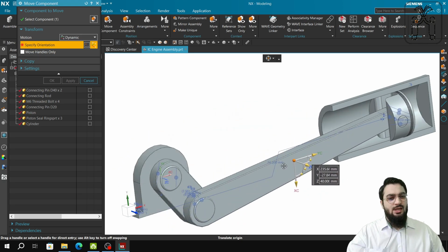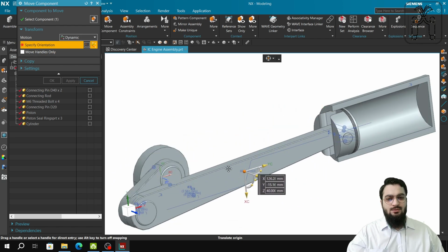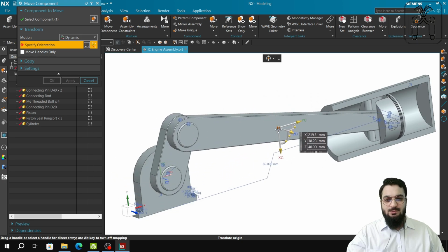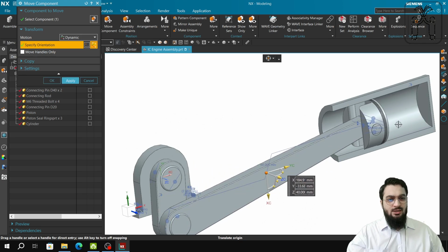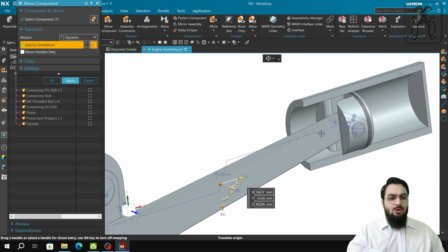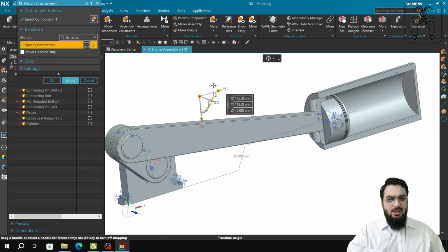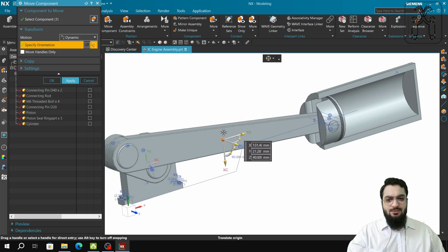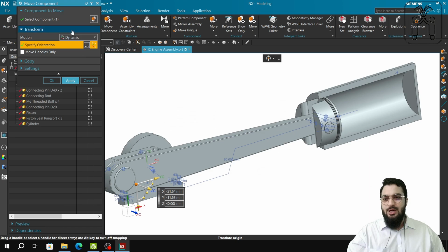So this is an IC engine assembly which has been properly constrained so as to achieve the desired motion. You can see that only the pins, crank, connecting rod, and piston are moving, and the piston seal ring is properly positioned with the piston even in the midst of motion. The cylinder does not rotate or slide anywhere. It is fixed, and the fixed pin also does not rotate anywhere.